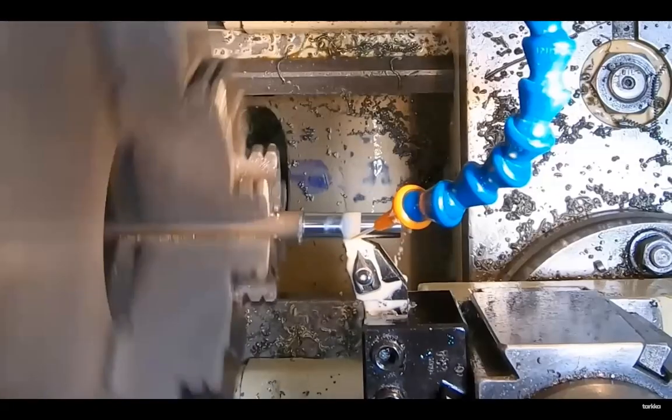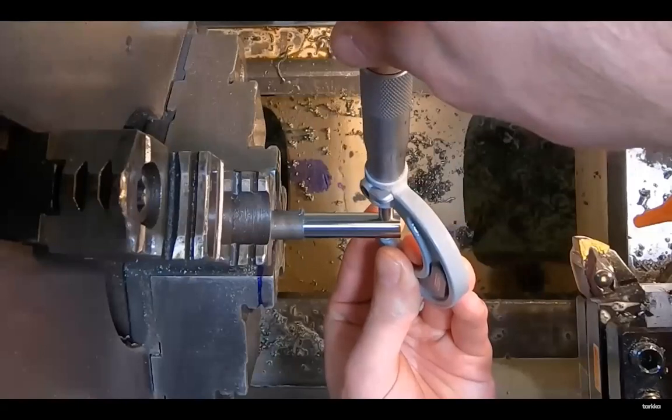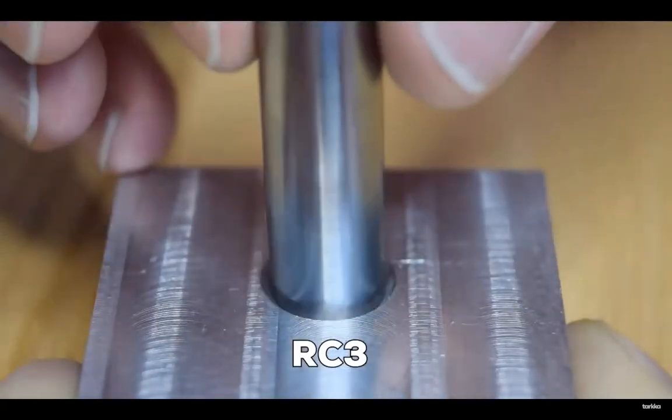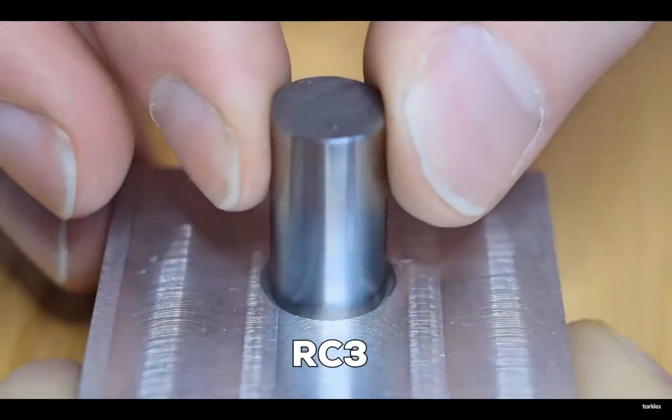For the rest of the fits in this video, we're going to have to work a bit to hit the tolerances, and you're going to want to be absolutely sure you need this in your design because you'll be paying for that care and attention. This is an RC3 fit, which is a tighter running fit. In general, this fit is going to have almost no perceptible play.